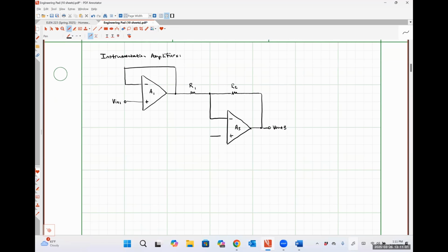Down here on the bottom side of things, I'm going to have pretty close to a mirror image of what I have on the top side, except for one distinct difference. So I'm going to show you that difference first. Instead of having feedback down here, which would make this a positive feedback system, which would mean I couldn't have linear amplification, I'm actually just going to take this resistor R4, and then I'm going to just ground out that leg.